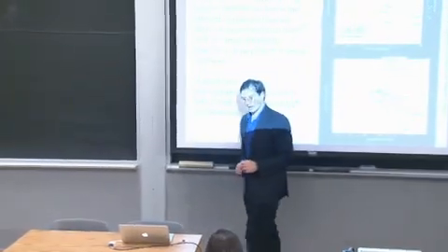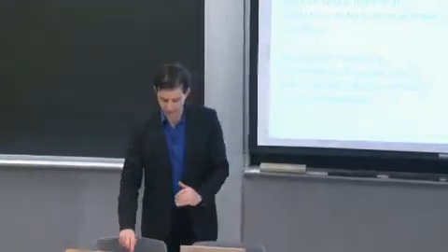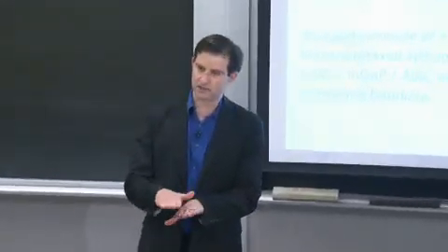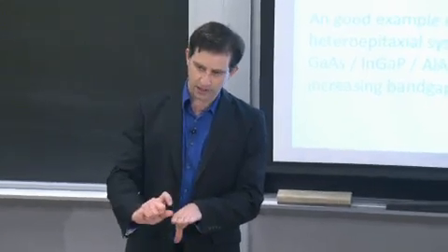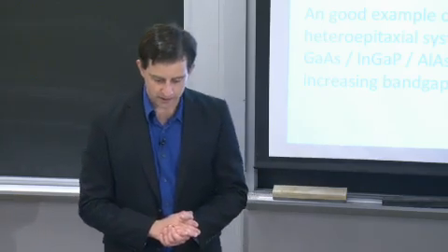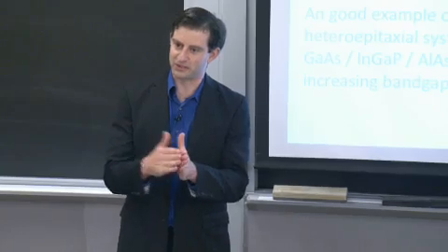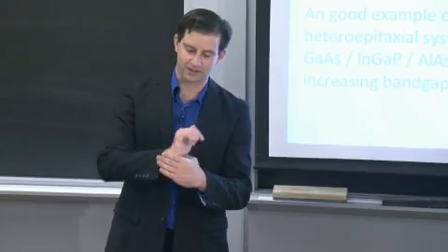So let me emphasize that in many semiconductor contact combinations, you would have a highly doped semiconductor right before the contact, a very localized region of highly doped semiconductor that would create a tunneling junction. In that case, the density of states at the interface doesn't matter because you have a tunneling junction. You're able to tunnel straight from the semiconductor into the contact.